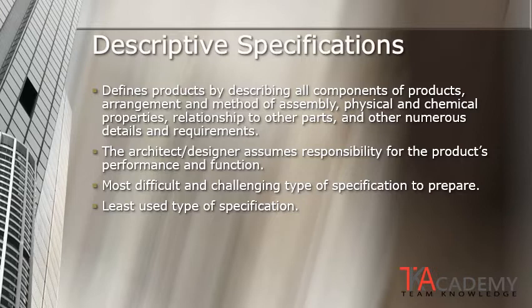Therefore, it is one of the least used types of specifications. In descriptive specifications, it is often the case that less is more. Putting less information in your specification works to your advantage because of the time and energy it takes to prepare that information and the open liability that one has for including it in your project requirements.